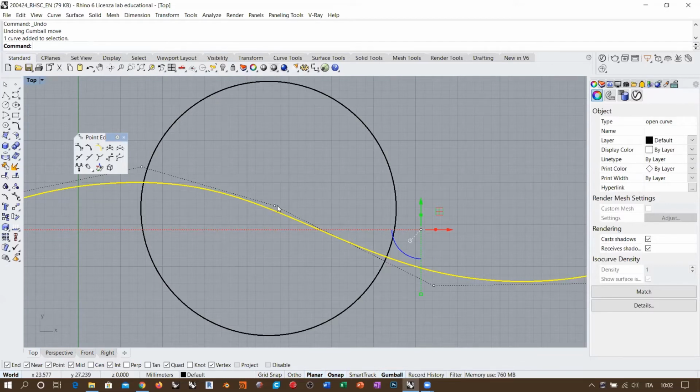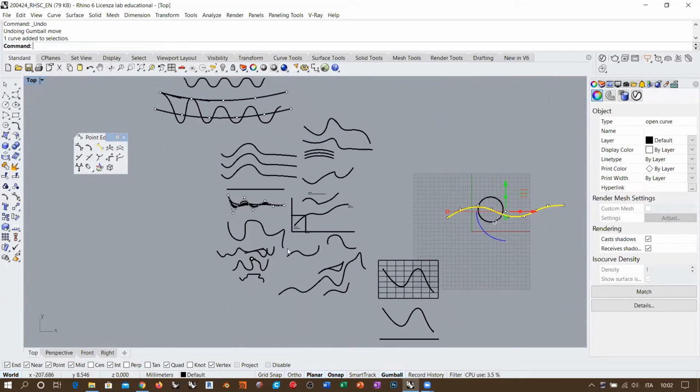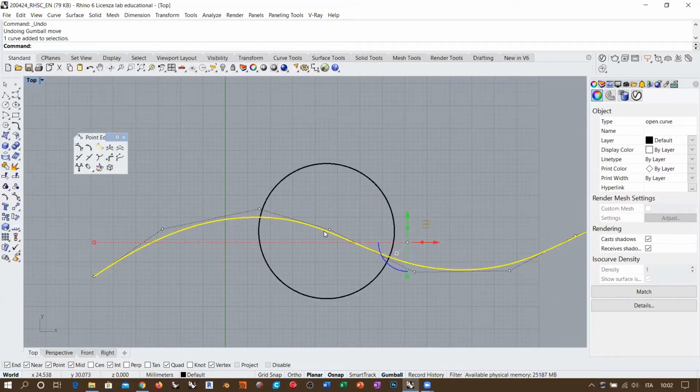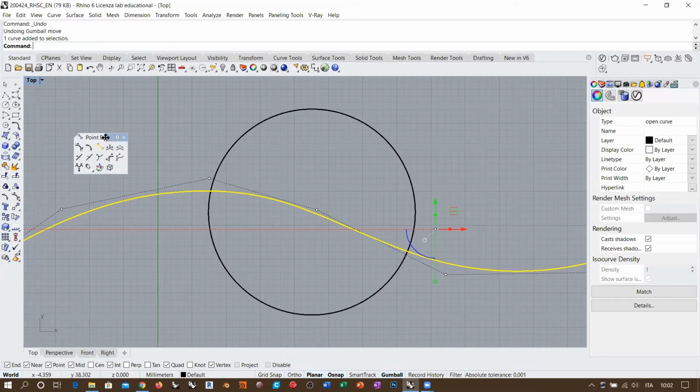And also, if I work with control points, I can always use, for example, the 3 rules that we saw about the control points distribution in order to create, for example, tangency, internal tangency, and flat areas. So it is best to have control points in one area. Now, the problem is this one. Normally one would say, okay, nice, I insert a control point here, so it's perfect. Well, actually it's not perfect.